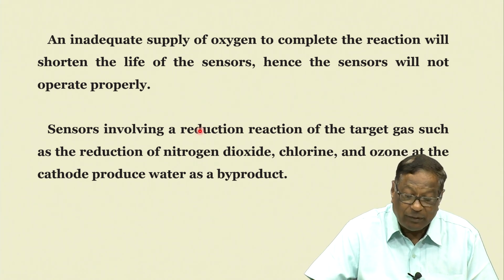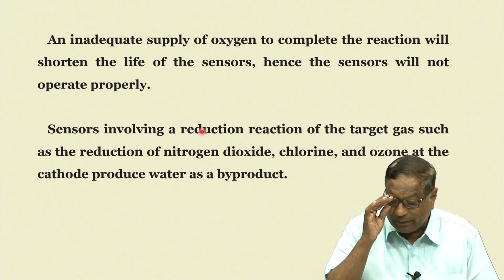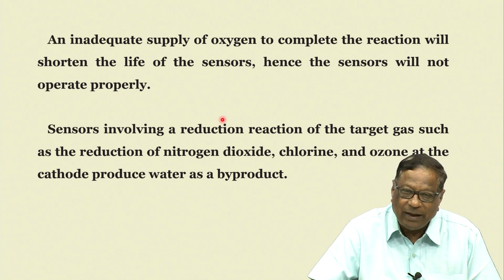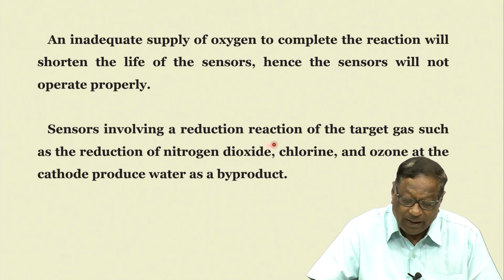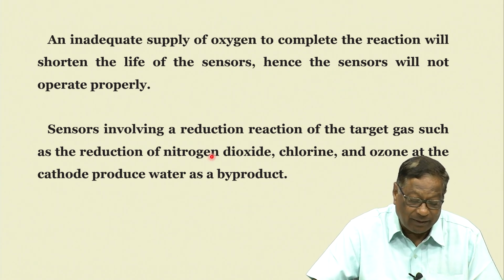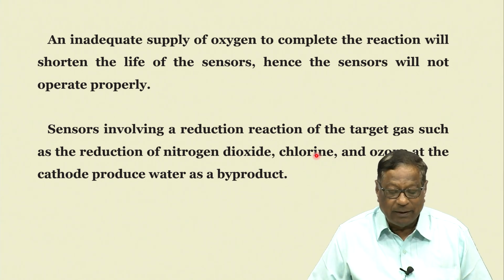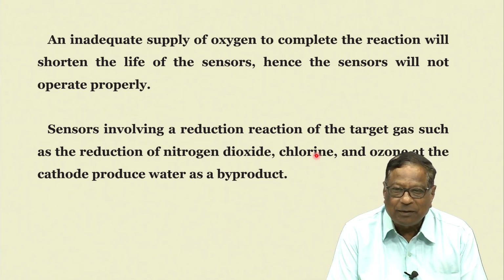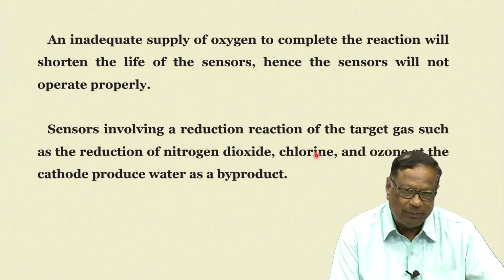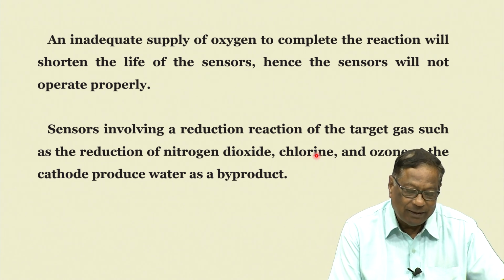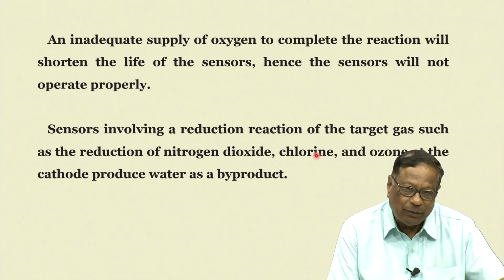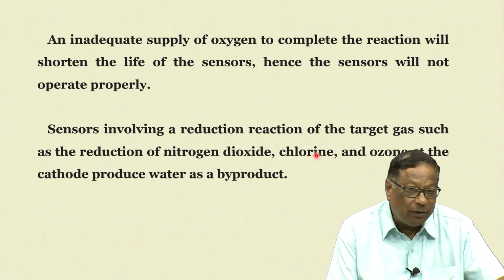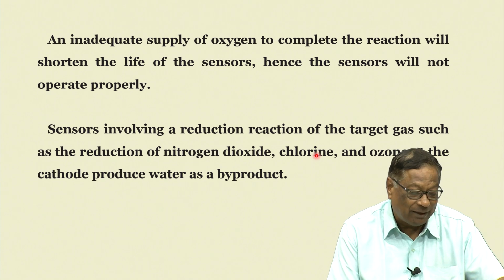So, sensors involving a reduction reaction, most of the things like SO2, NO2 etc., they are all reduction reactions. They target the target gas. So, nitrogen dioxide, chlorine, ozone, they all produce at the cathode water that comes as a byproduct. So, wherever there are oxygen atoms in the analyte, there will be water as a byproduct. So, the typical reactions will be going on, it will not dry out. That is what I am trying to tell you.